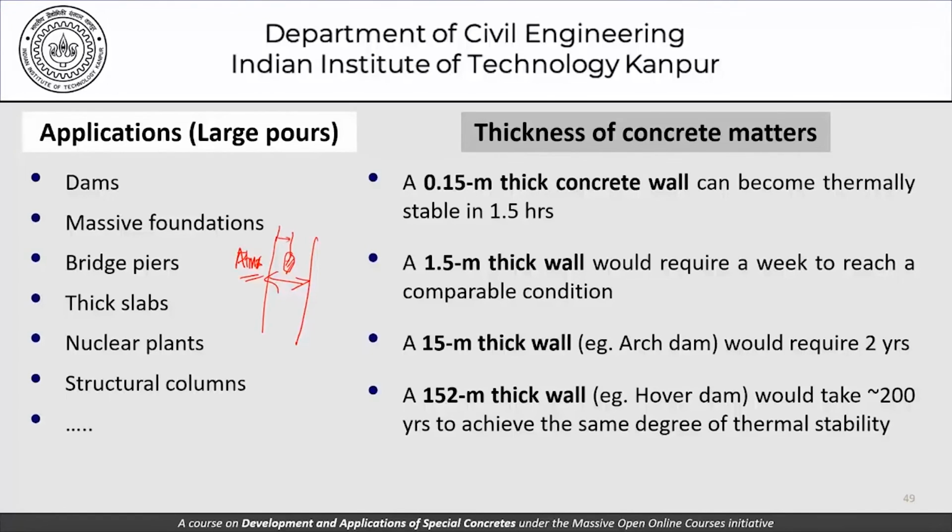If it was a 150 mm thick wall, just 1.5 hours. If it was to become 1.5 meters, it will be about a week. If it becomes 15 meters, which is something you would expect in something like an arch dam, it could take almost 2 years. And if it becomes 150 meters, then it could take as much as 200 years to achieve the same degree of thermal stability.